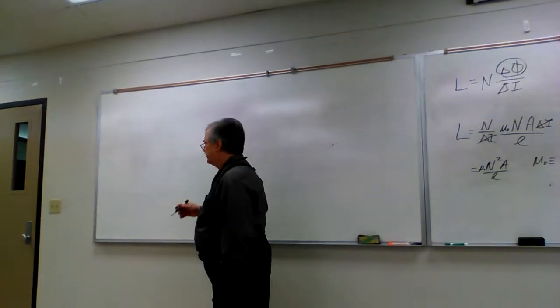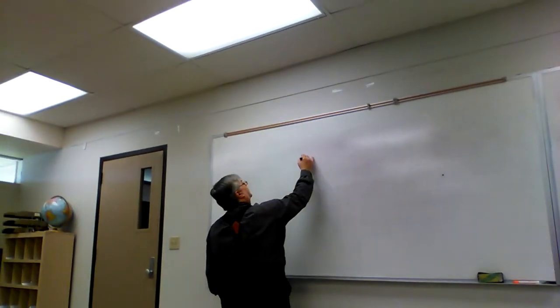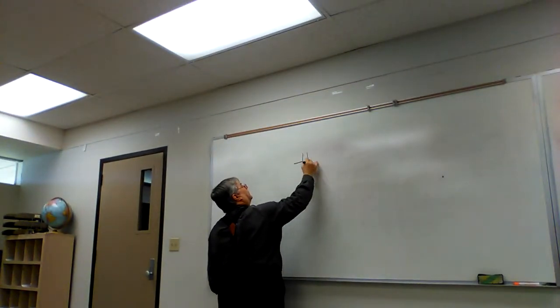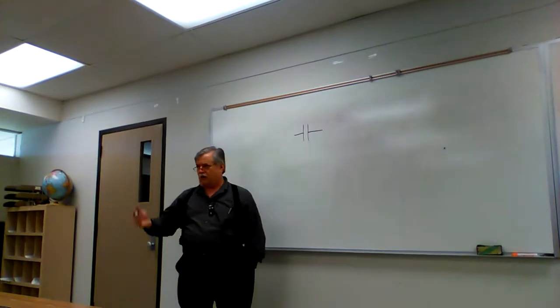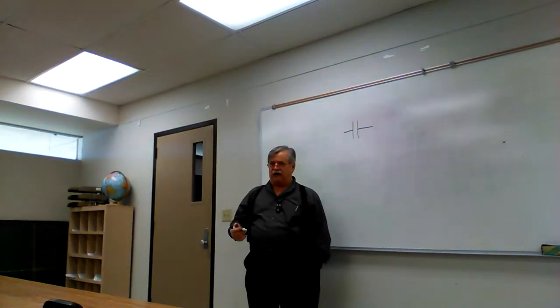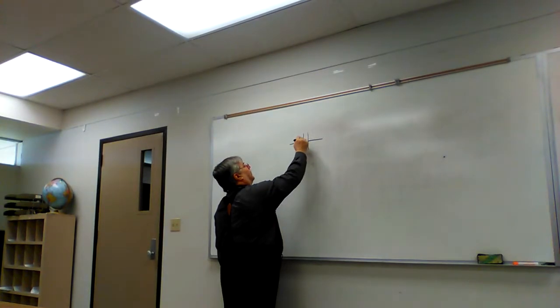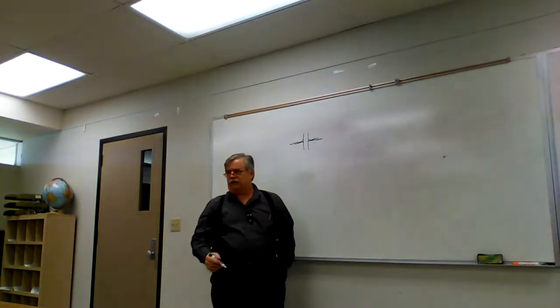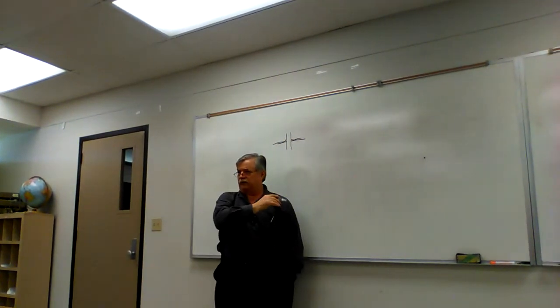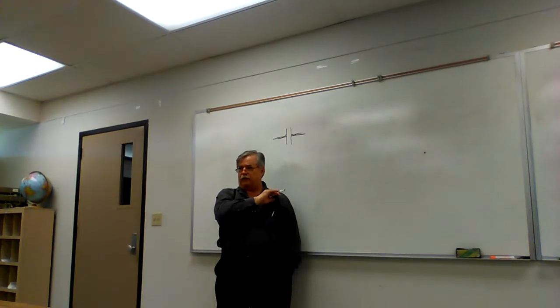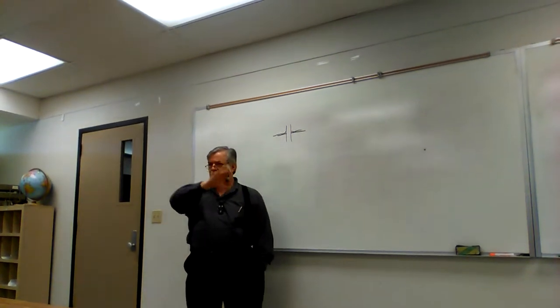It means when you have a circuit and you've got a capacitor, you first turn on the voltage. You apply a voltage. Current is going to start to flow. And as it flows into and stores a charge in that capacitor, voltage is going to increase.